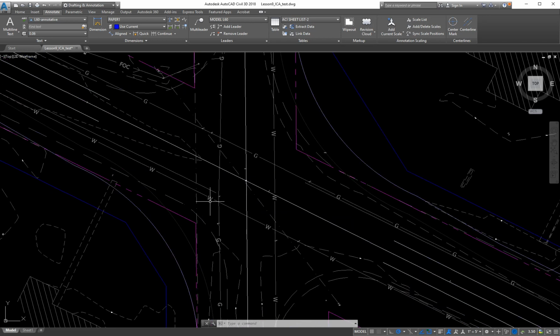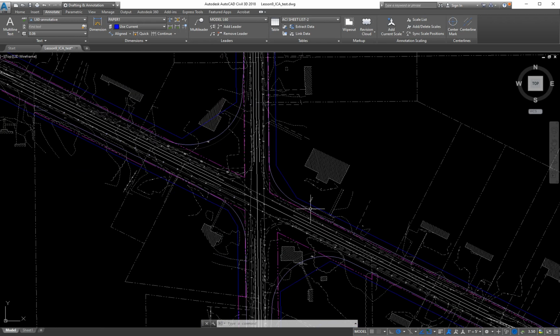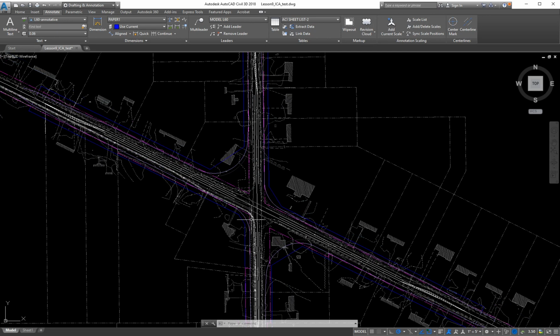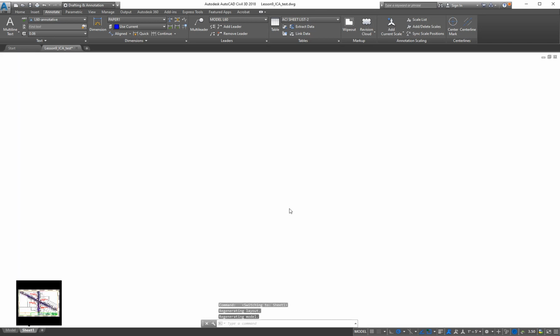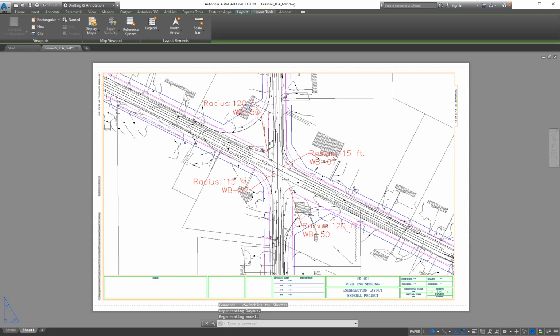And then the real text in here is different line types. This is a water line, that's a gas line, right? And sometimes surveyors will leave notes in here, but we usually hide all that when we plot. All right, so see, there's no dimensions, there's no callouts in the model space, and that's how we like it. And then we put all of that over here in paper space when we flip to paper space, right?